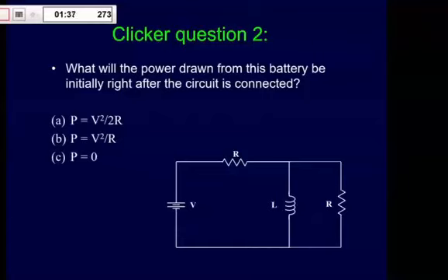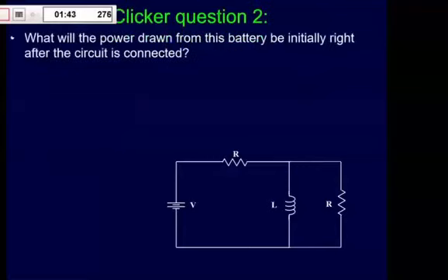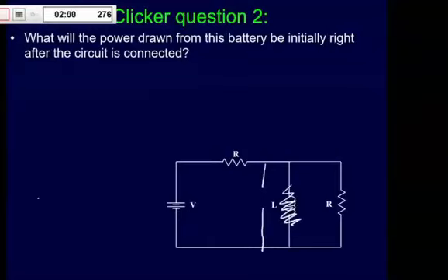Okay, so I think we've thought about this, and I'm happy with our results. So we got this here. So let's look at this. So this is a situation, again, where at time 0, this just blocks all current. Okay, so this inductor behaves like there was just a blank here. And so it doesn't actually let any current through.